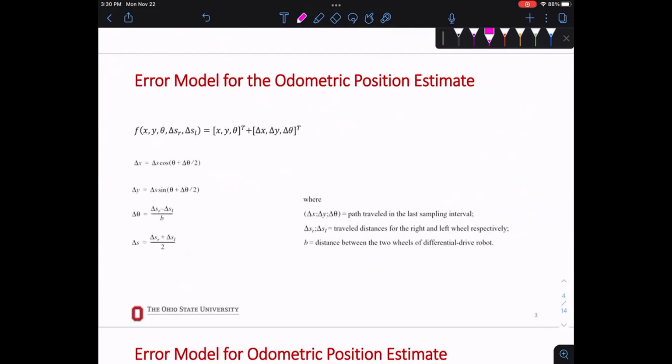that are not desirable. But we are counting it as if, okay, if we had those X, Y, theta position, plus some extra distance or angle in that direction. So that's going to be our function. You're going to look at that. Things that you're controlling here, or the input of our function, is X, Y, theta, positions in X, Y direction, theta, and then delta SR and delta SL, the distance that right and left will move, right? So if those are our input to the system, the output we have is actual motion in X, Y direction with some error. So the error is shown here with delta X, delta Y, delta theta.